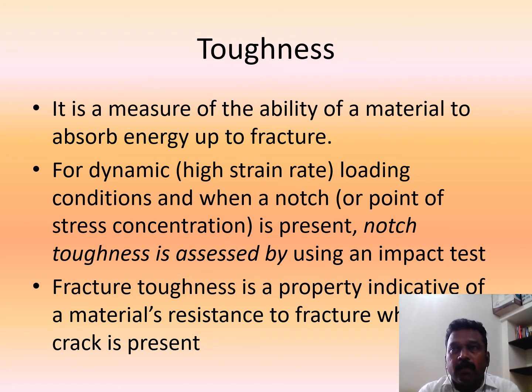Without a crack, the material deforms. In the tensile test, there will not be any crack in the material, but it will deform and then fracture. That is static loading without the presence of a crack. Whereas in fracture toughness, we need to initiate a crack. We have to initiate a crack by using a notch. That is fracture toughness.